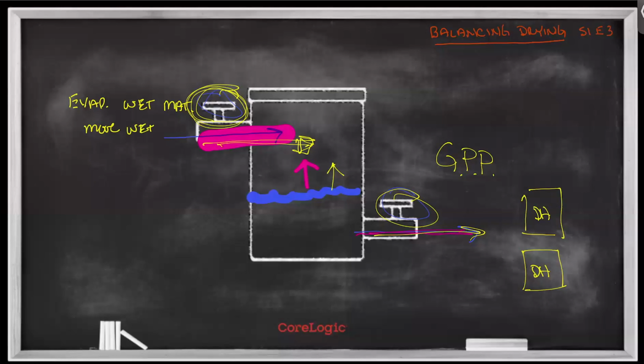that you didn't discover. So are there affected areas that you didn't discover? And is that the reason why the installed dehumidification wasn't adequate? Will adding a dehumidifier fix that? Well, no, it won't for several different reasons. Number one, if there's more wet material that you were not aware of, you're not monitoring that material. How will you know if it ever dried, right? You probably didn't extract that area. Is there bulk water? And evaporation is the wrong way to deal with bulk water, right? It should be properly extracted.